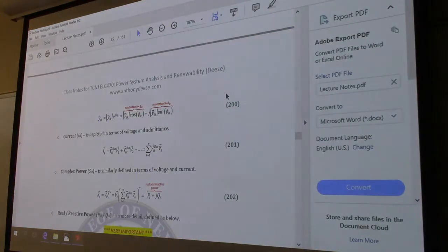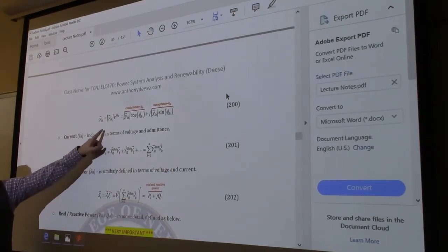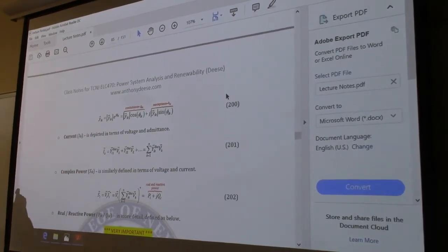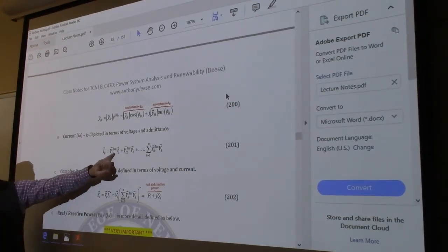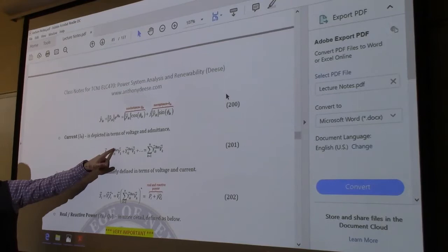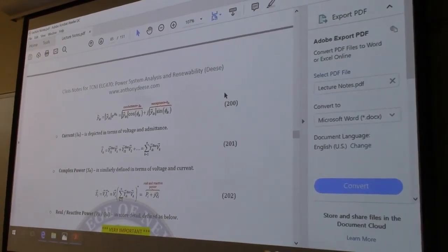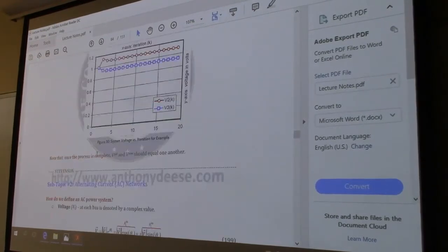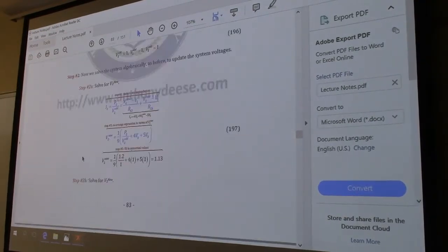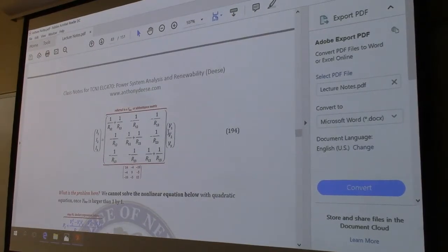And so the form that they show it, there's a difference. Yik represents the admittance between two different buses. Yik with this superscript bus is going to be the ik element of the admittance matrix, which you know as the matrix we use for nodal analysis.